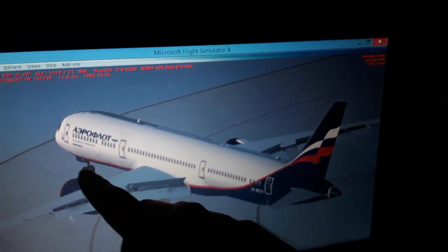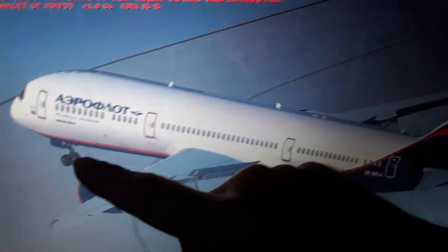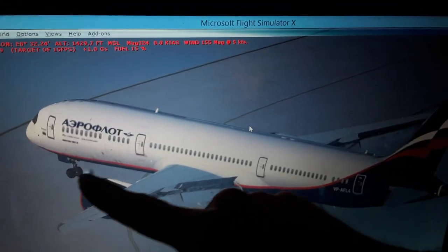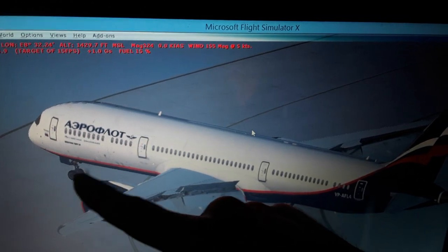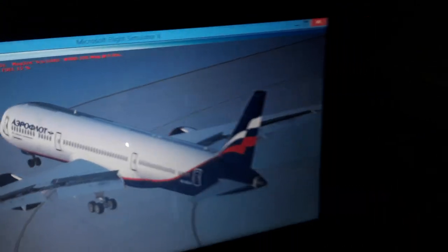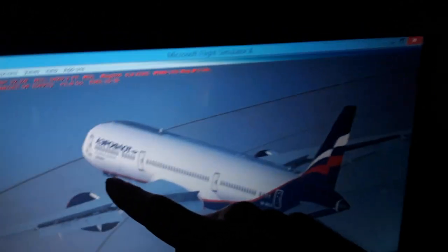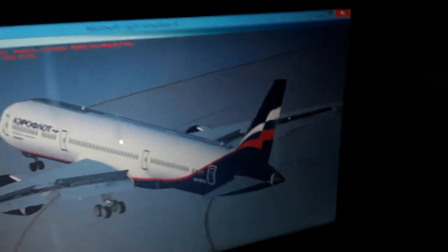As we increase the airspeed above 80 knots or 144 kilometers an hour, only the rudder becomes aerodynamically effective and is used for steering. Then the nose wheel is locked into zero position or very small deflection like half or 1 degree. So we only have the rudder aerodynamically effective to control the aircraft above 144 kilometers an hour or 80 knots, and the nose wheel is locked to zero deflection.